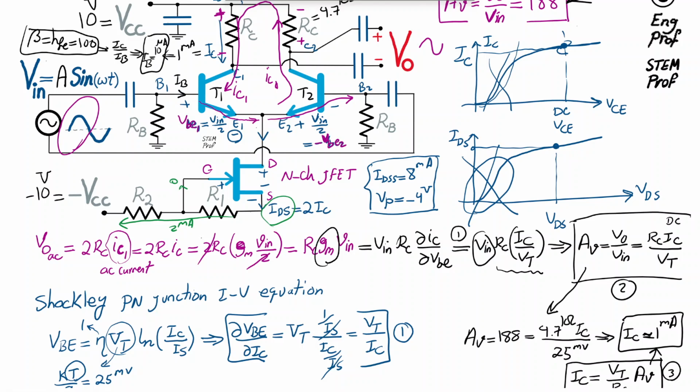So 10 microamp. And the DC drop across RB is just 10 microamp times that RB. So if I select RB to be 1 kilo ohm, we have a degree of freedom there. I mean, depending on what other criteria you have in mind, you can select a different value for RB.